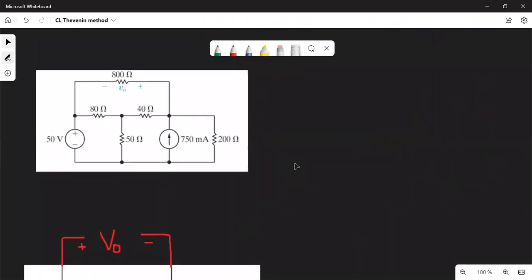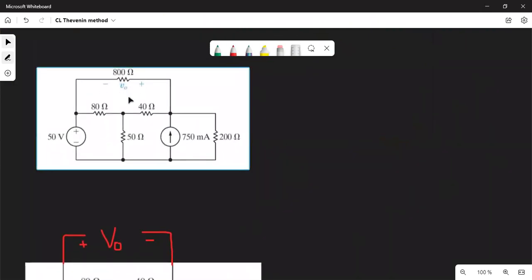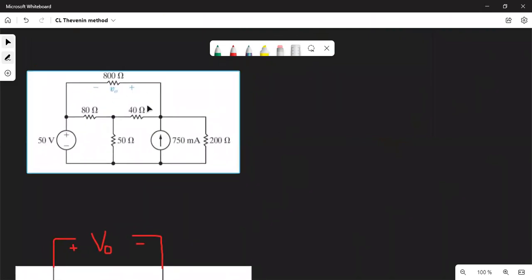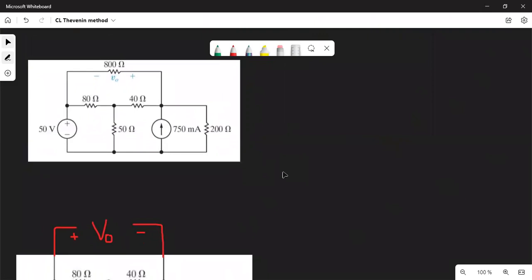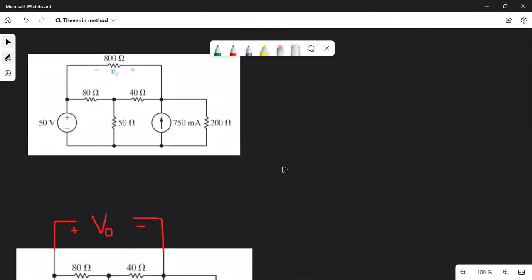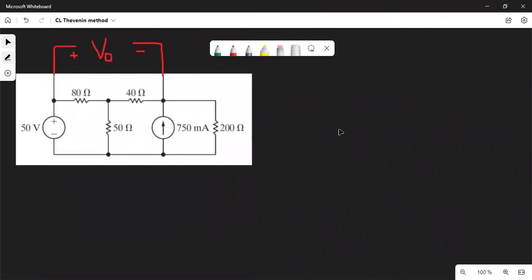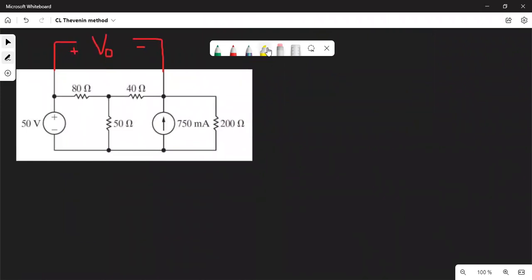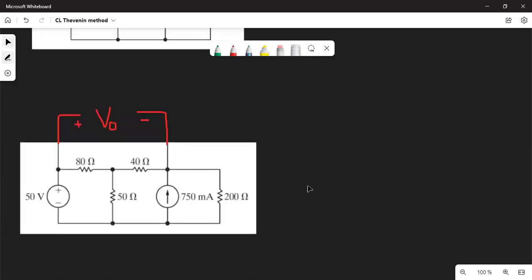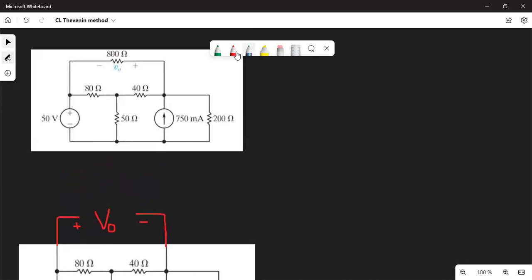So we should find this V0 here, in this equation. Let's use the Thevenin equivalent in order to identify this V0 point. As you can see, in order to find the voltage across any resistance, firstly we substitute this resistance with an open circuit. Then we find this open circuit voltage, and come back and calculate V with the formula that we showed above. In this case, our loading resistance is 40 ohms.